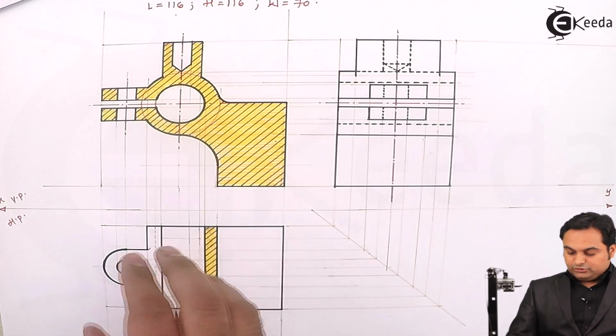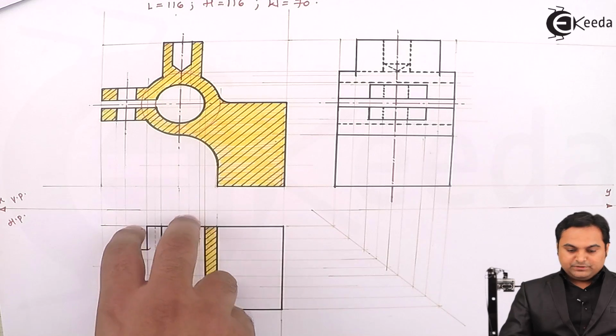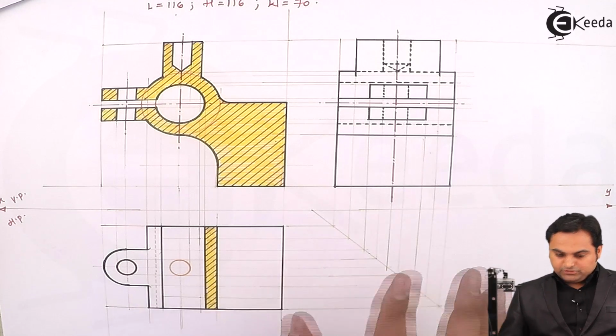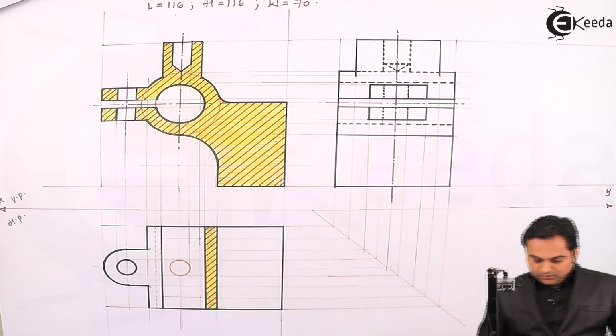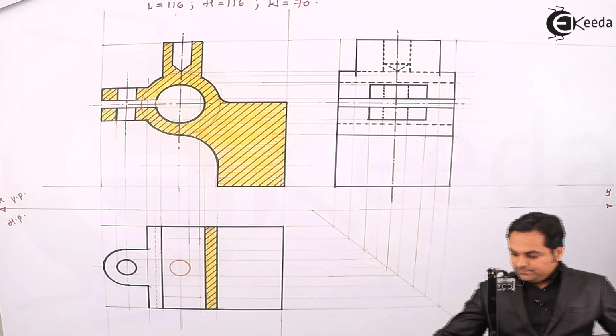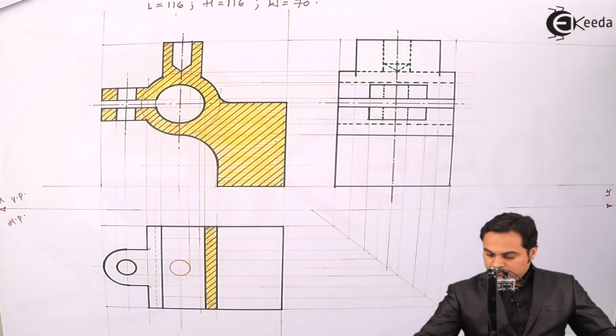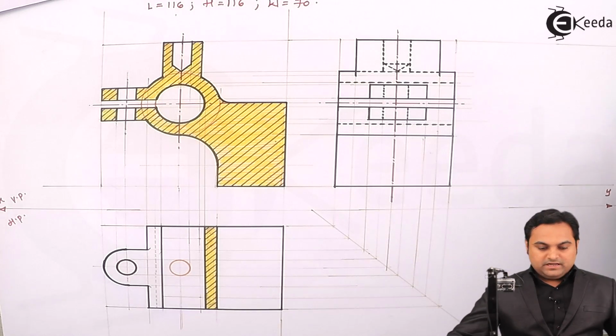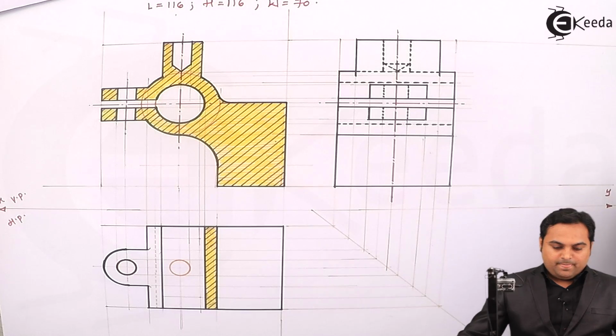And then this top rectangular surface has been removed, and the sectioning is there only up to this part. So this will be the sectional top view, and here I'll say that only the dimensioning part is being left, and I'll locate the cutting plane as well.